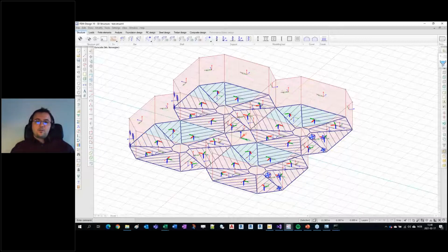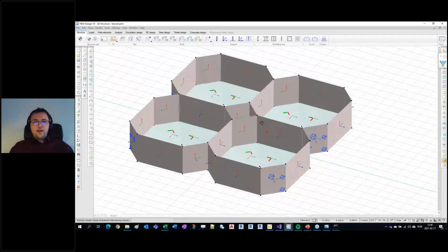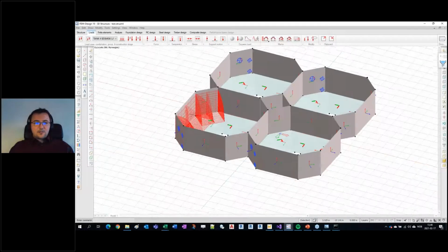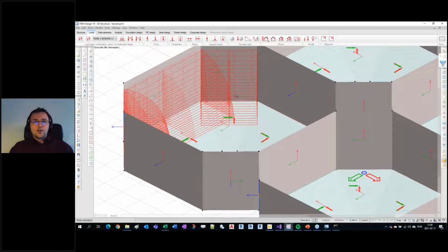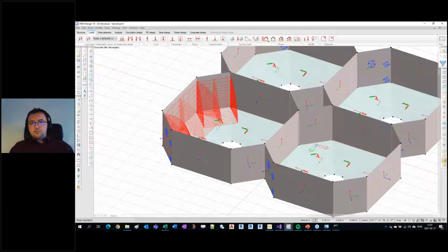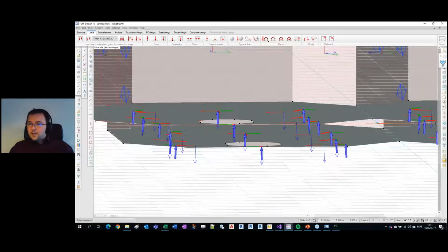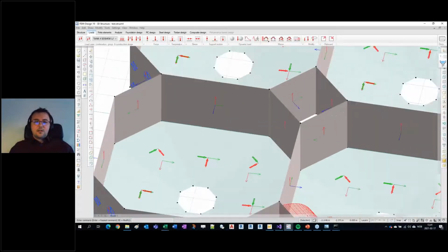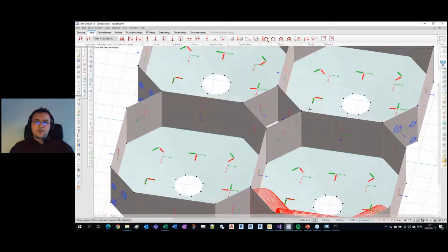And the main issue was that once one model was done for one project, it was almost impossible to reuse that model for another project. Because if, for example, this tank is a bit wider, let's say 1 meter wider, then one needs to move all these walls there, all these walls there, and the loads, which are relatively complicated, also need to be moved and stretched out. And these bottom plates are modeled under an angle, maybe not so visible here. So pretty much one would need to erase the whole model and start to build it from scratch.